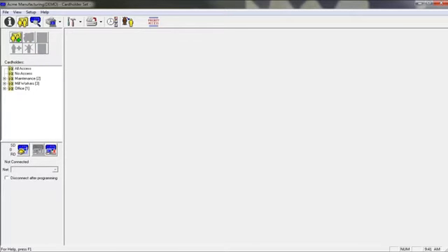The on/offline installation button is located in the lower left-hand corner of the screen and is pictured as a yellow telephone. By selecting that icon, AccessBase 2000 will connect with the telephone entry and/or access control panel, either through dial-up or direct connect, depending on what we're using. The upload button sends information from the computer to the panel and is pictured with an upward-pointing red arrow.